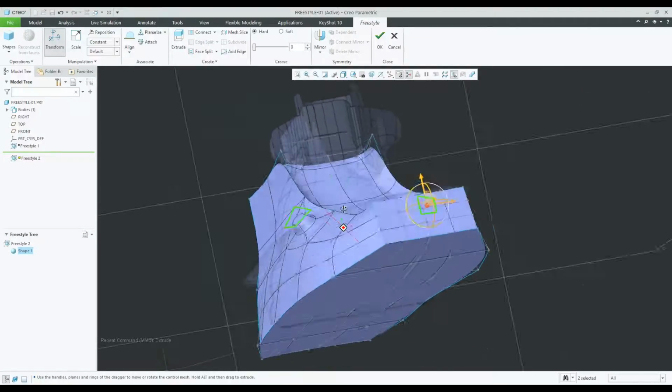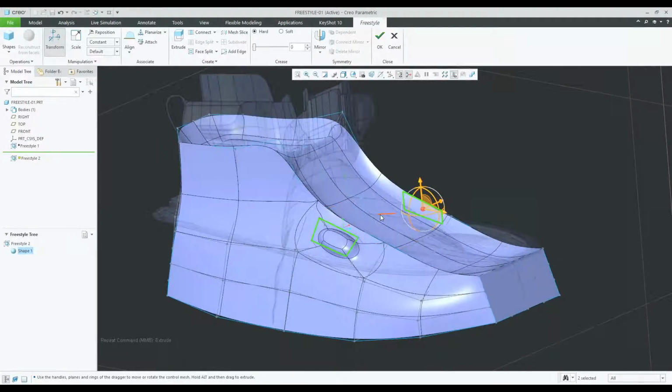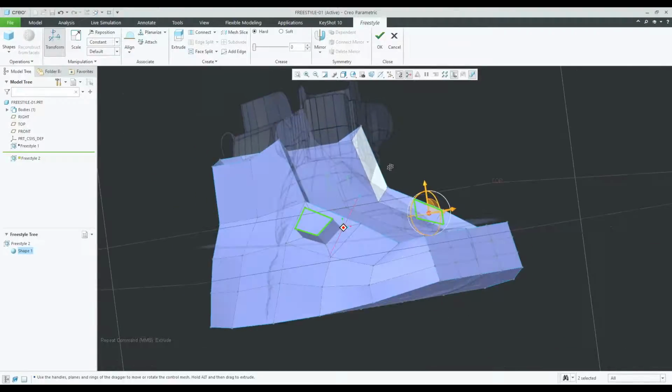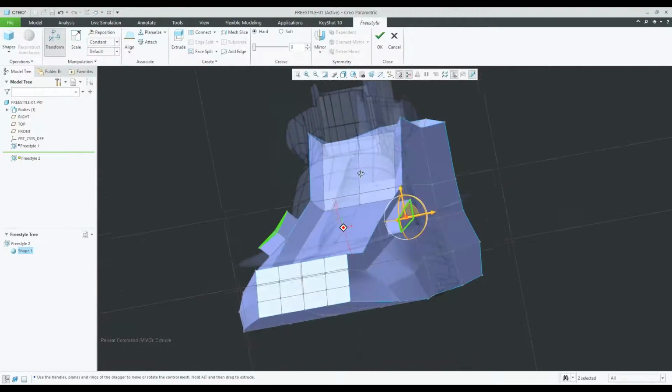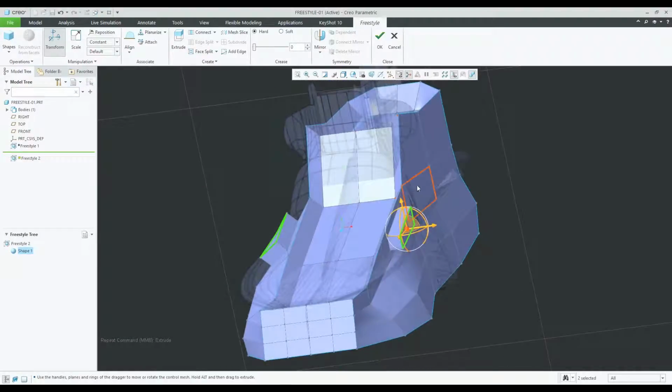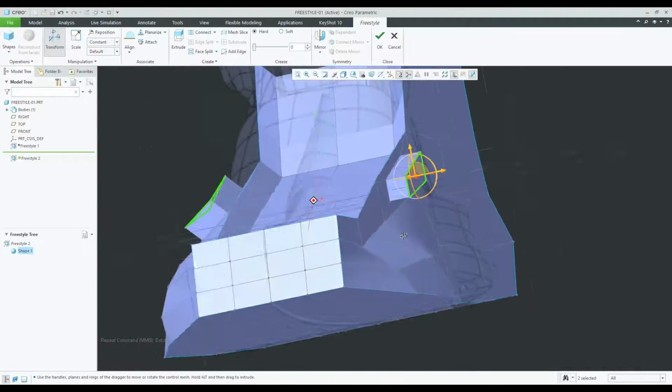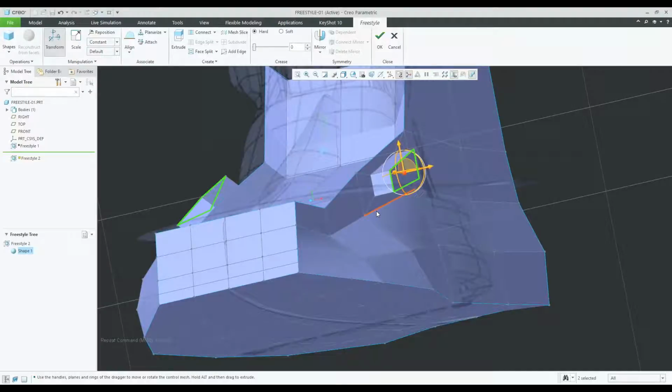You can see that right now I'm in smooth mode, so it's taking the hard edges and creating a smooth surface. If I come up here, I can select box mode, and that gives me this hard edge box mode to model in. Sometimes this helps in modeling, giving me a harder edge to see exactly what I'm doing here.